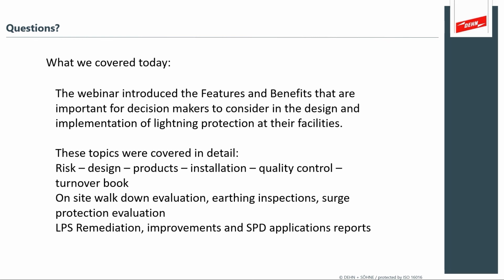We have one more question that just came in. John asked, I got confused about where is the best location for the control and data SPD? Close to the equipment to be protected, or at the entry of the cabinet? For best practices, it's both ends. You put the SPD at the point of use, the flow meter for instance, and then at the marshalling cabinet entrance, so that it's as close as possible to where the energy is entering the cabinet.